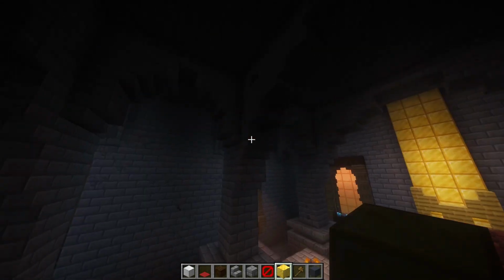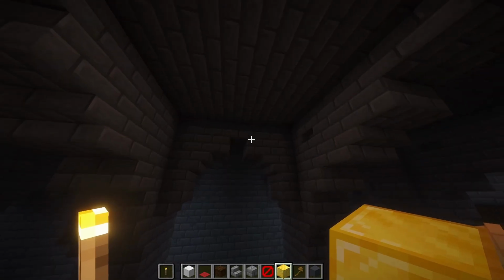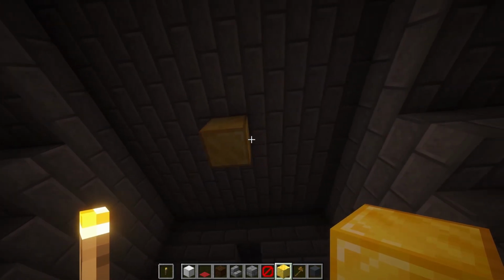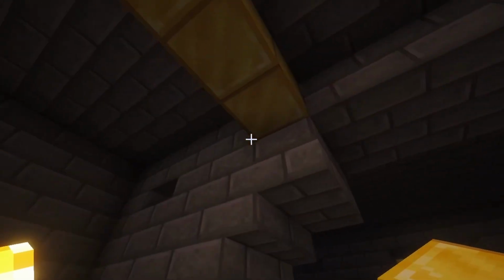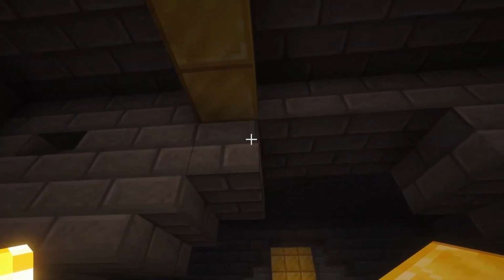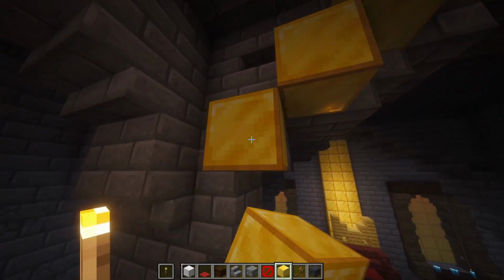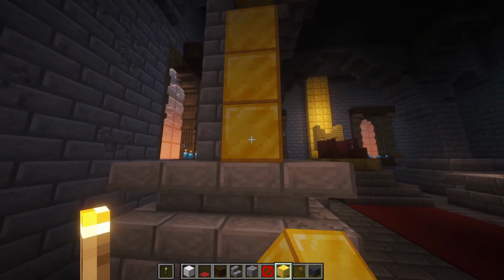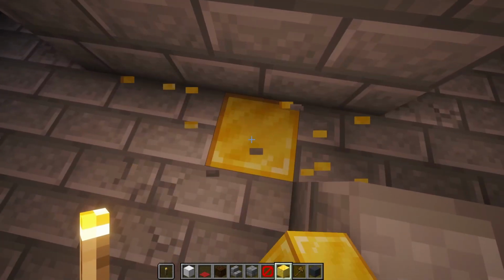So let's do a final check to see that you guys understand. Okay, so let's say there's a weight here, right? Where would the weight go? Well, half of the weight would go here, and it would go onto this arch. It would be handled by this arch. This arch would then send the weight down itself, all the way down to the column, right? And the column would take this all the way down underground into the foundation.